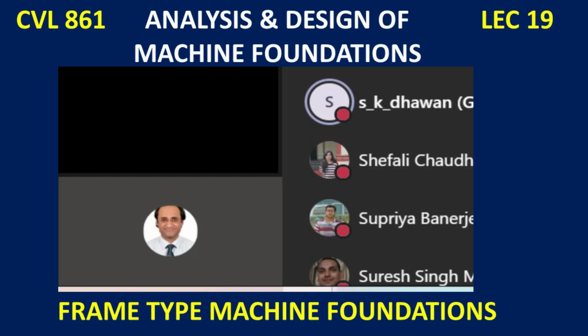After knowing the geotechnical investigation report, we will make a design basis report explaining the total structural system, that this building is a frame structure, shear wall, whatever it is, and these are the types of loading, and this is what we are going to do.